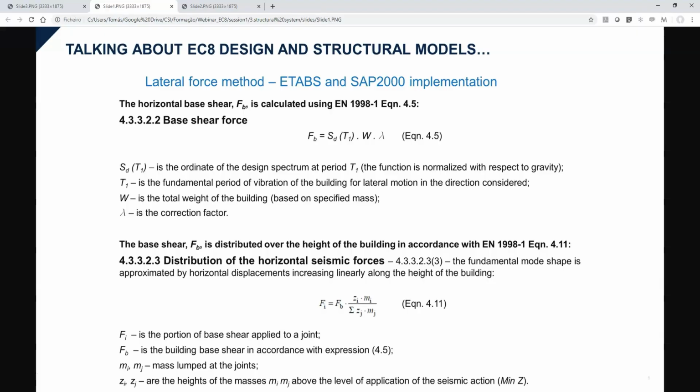We had defined our ETABS model with 50% stiffnesses. We will use a modal analysis to determine the fundamental periods which the structure uses to determine the seismic load. We could choose either the primary or global structure for the modal analysis, but we will choose the global one, as it seems most suitable to represent the three-dimensional global behavior of the structure and ensures we are closer to the actual natural frequencies and periods.